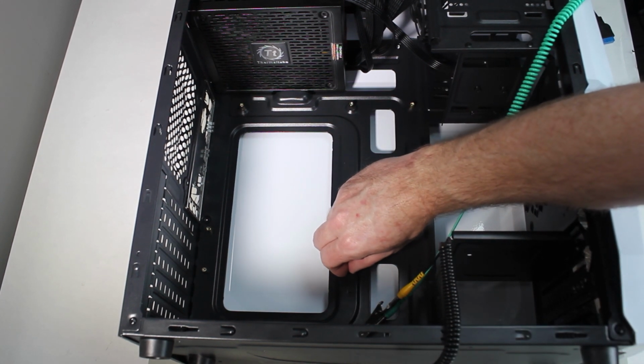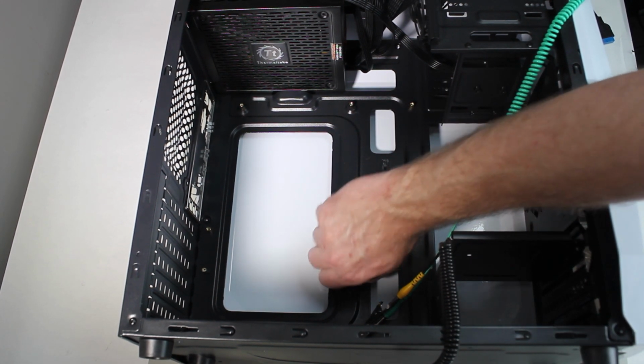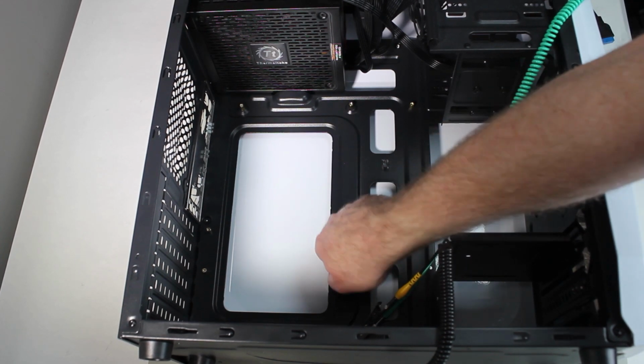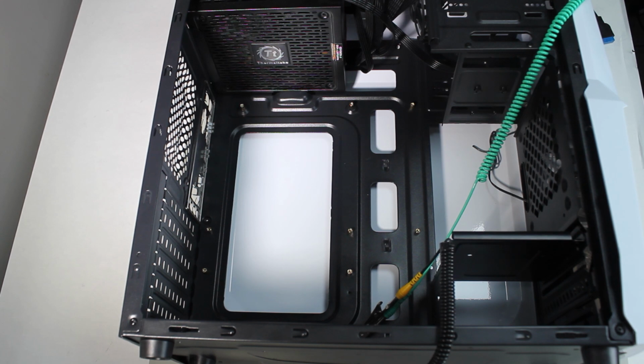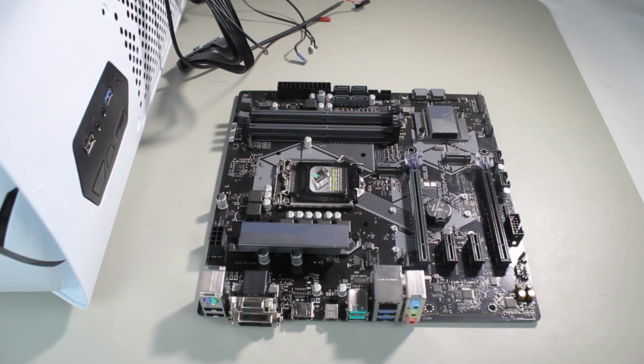In some computer cases, you may need to use a little force, particularly if the case is new. This is because the thread may be a little blocked with material or incomplete when manufactured. When you feel that the standoff is screwed in all the way, stop screwing it in. If it is only partially screwed in, try turning a bit harder. If you are having no luck, remove the standoff and try again. If that does not work, try using a different standoff, as maybe the thread in that standoff is damaged.